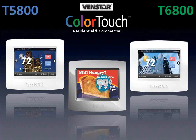The residential one will have the typical residential language like wake and sleep, whereas the commercial one will say occupied and unoccupied. You'll also have on the commercial one the ability to lock out screens with a passcode so people can't mess with it. The residential one will have things like dual fuel heat pump operation, so there'll be a few differences between the two of them, but most of the main stuff is going to be the same in how the thermostat is used and how it's navigated.